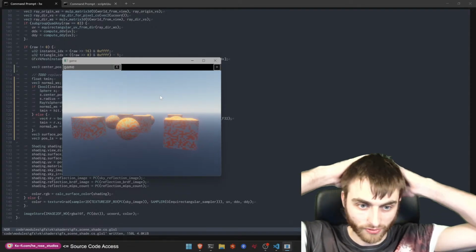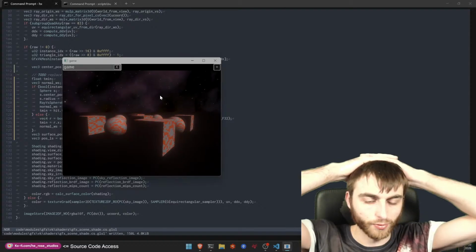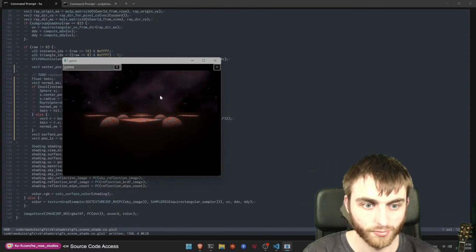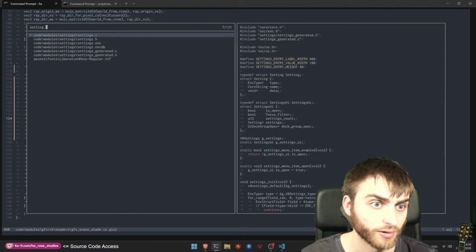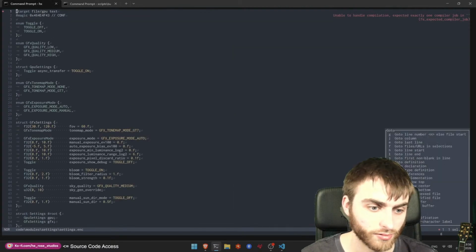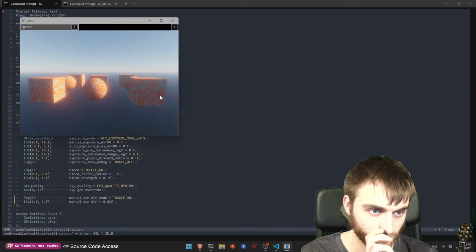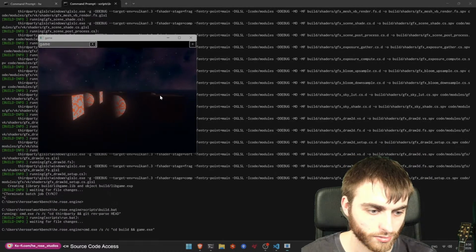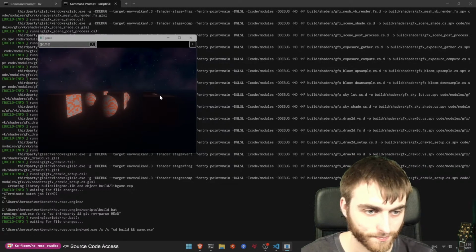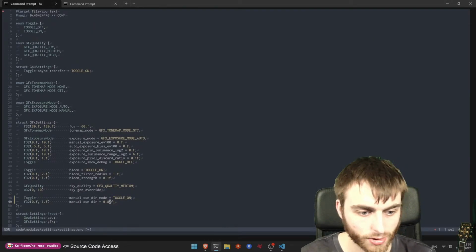So we should probably fix the sun to a certain place. Having changing times of day is not really going to be helpful when programming a material. So we can go into the settings quickly and change the default value for manual sun direction to on. We can stick it at, well, it'd be nice for it to just be a little bit higher. So maybe 82.